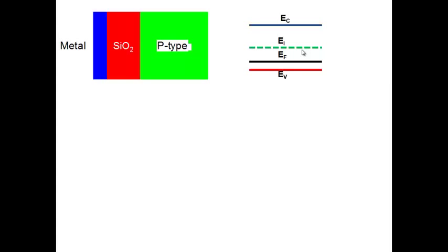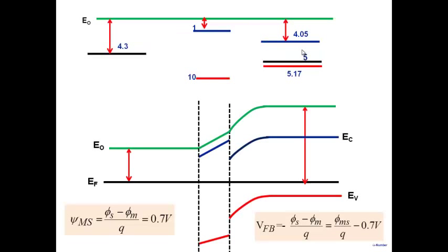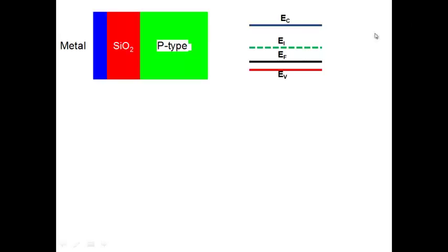All right. Now, as I said, what we want to do is gradually progress to doing a more quantitative analysis of our MOS capacitor here. So this is the condition that I've shown here in flatband, right? If you apply a gate voltage equal to flatband voltage, this is what would happen. All the bands are flat, right? Now, let's have a couple of definitions. Psi, the potential anywhere in my semiconductor, we know, is minus Ei by q. You can define it in many ways. Psi can be equal to minus Ec by q, or minus Ev by q, minus E naught by q.